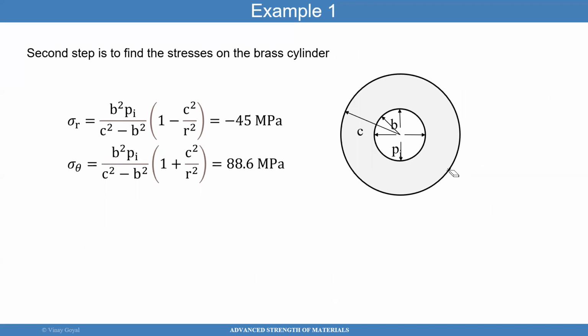So that equation is simple. I discussed that in the pressure vessel equations. This pressure is known, the internal pressure, PI. And so if I know PI, the pressure inside, and I know the internal radius and external radius, that's a very simple and straightforward calculation. The stress at R equals B, which is where I'm interested, can be easily calculated to be this much, which makes sense that the stress should be radially in compression because the hollow cylinder is getting compressed against that core.